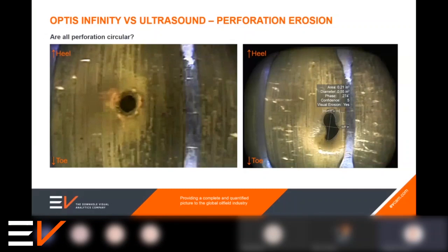But a number of different technologies that we've got identified, and 3D imaging is certainly one of the areas that we're considering. But for what we've done to date with the capture of the 360 field of view and with the image processing that we've got for measurements, certainly in the circumferential and axial plane, a 2-dimensional measurement, let's say, I think that's been a terrific step forward. And combining that with other measurements, whether it's a multi-finger caliper, ultrasound, or a thickness tool, that can potentially give us some additional information, and is actually a very powerful thing to consider.